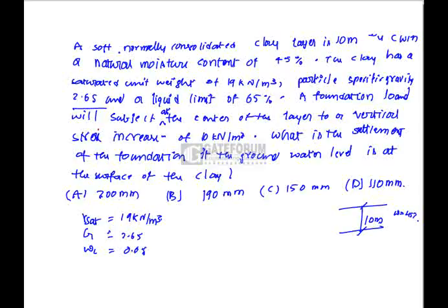A foundation load will be subjected at the center of the layer, with a vertical stress increase delta sigma. The vertical stress increase at the center is given as 10 kilonewton per square meter. What is the settlement of the foundation? If the groundwater level is at the surface of the clay layer, we have to find out the settlement.